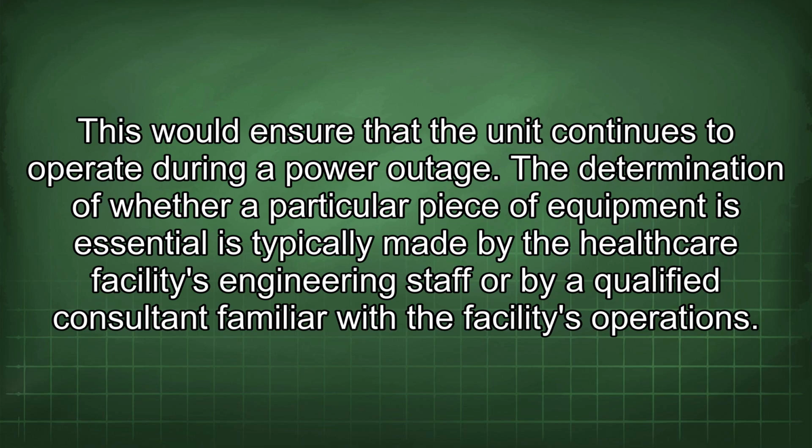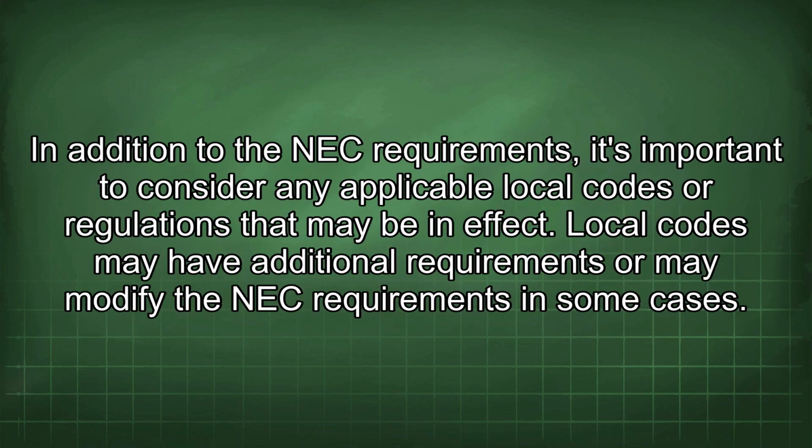The determination of whether a particular piece of equipment is essential is typically made by the healthcare facility's engineering staff or by a qualified consultant familiar with the facility's operations. In addition to the NEC requirements, it's important to consider any applicable local codes or regulations that may be in effect. Local codes may have additional requirements or may modify the NEC requirements in some cases.